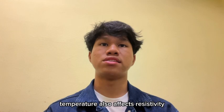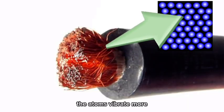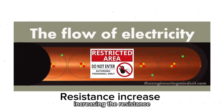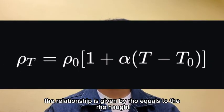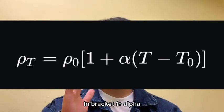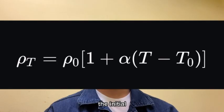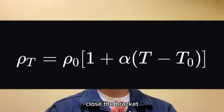Temperature also affects resistivity. When a conductor gets hotter, the atoms vibrate more. These vibrations make it harder for electrons to pass, increasing their resistance. The relationship is given by ρ equals ρ₀ in bracket 1 plus α, or the temperature coefficient of resistivity, in bracket the final temperature minus the initial temperature, close the bracket.